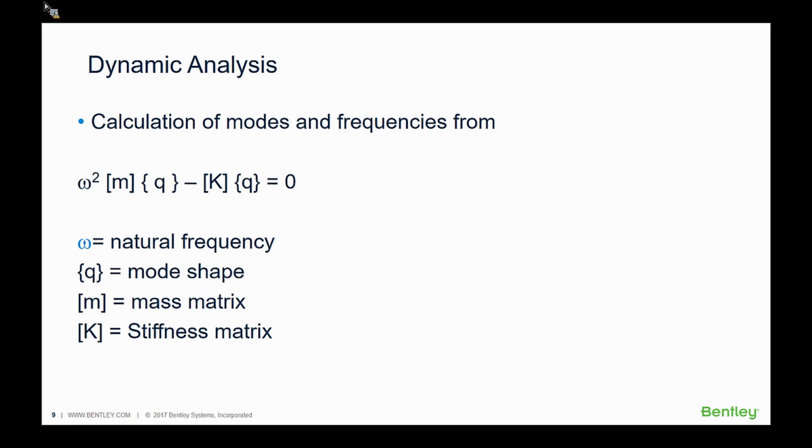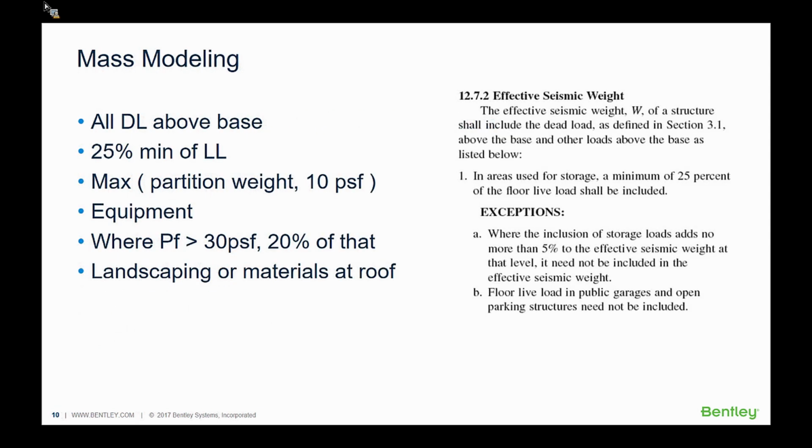Results of the eigensolution can vary significantly depending on how the mass and stiffness are modeled, and this can have direct impact on the results of a dynamic analysis. Hence, it's vitally important that proper care is taken in mass modeling and stiffness modeling.